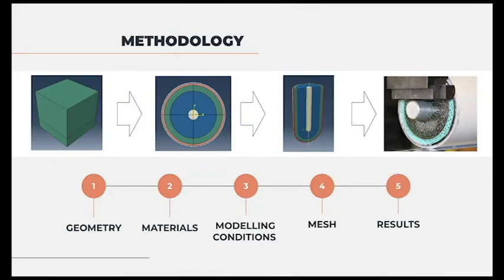We began by modelling small cubes of materials we wanted to get more information from. This was how we decided on the constitutive models we wanted to use to define each material. Once this was decided, we were able to move on to the two-dimensional cross-section of a simplified assembly. Then, to see the effects that the complex loading situation may have, a three-dimensional model was created. Finally, we validated our results experimentally.